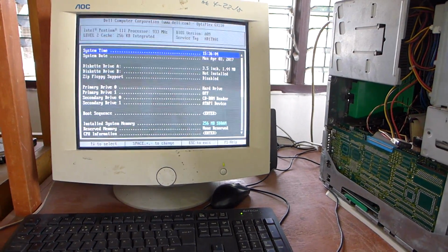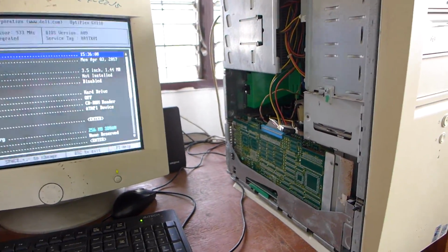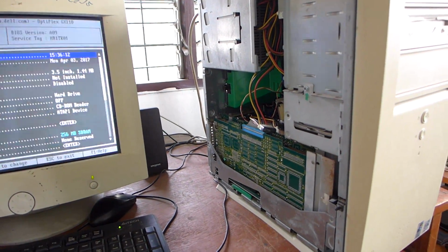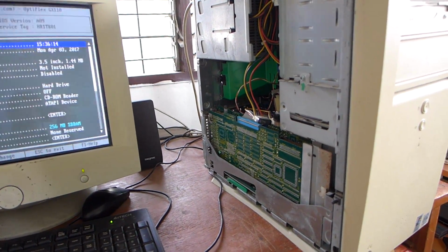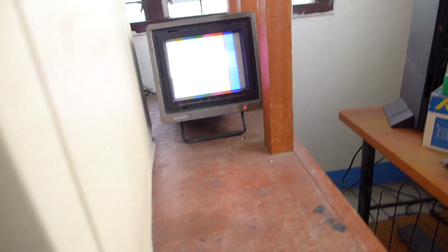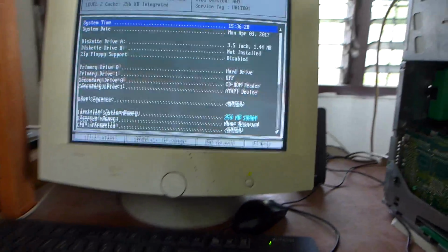Once your DTL-H2000 equipped system is up and running, the easiest way at this step to know if your DTL-H2000s are functioning correctly is to look at the TV output of the H2000, and you should see a color pattern like this one. If you're seeing that, it's a good sign that the boards are functioning correctly.